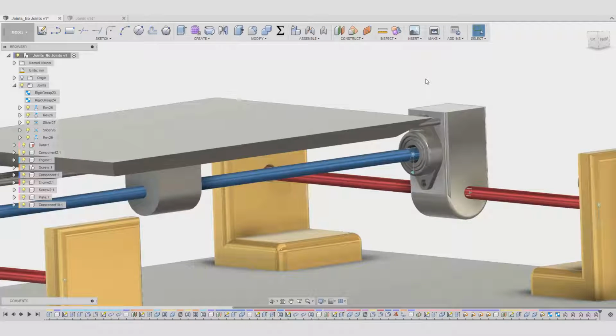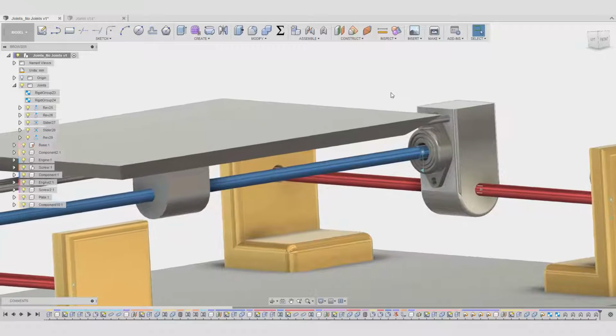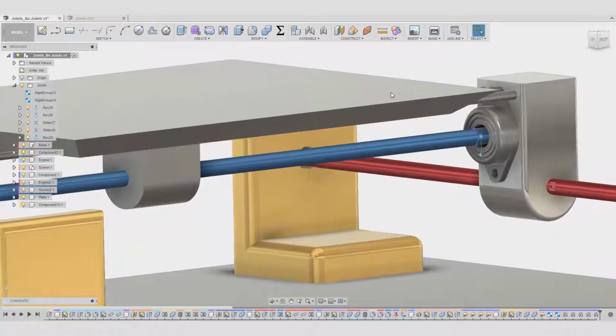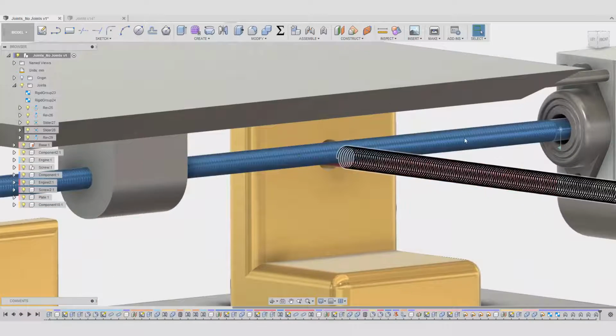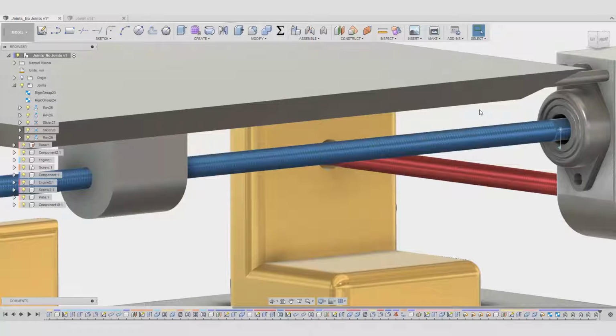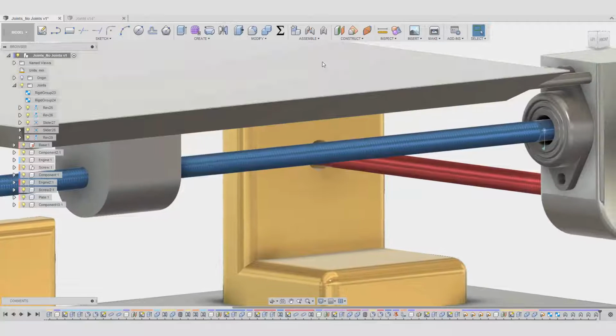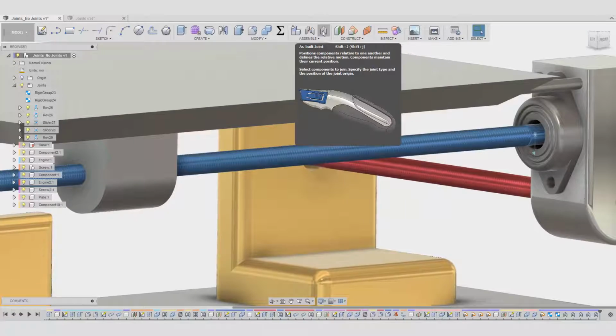By the way, I could have actually also used a rigid here if it doesn't really matter for you the effect that the screw is turning. So just choose a rigid. But if it's something that you're going to show, and it's very important to you to show the effect of the screw, how it's turning, then you can use the Revolute.